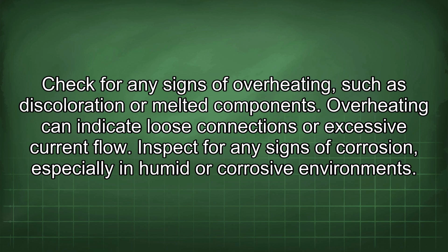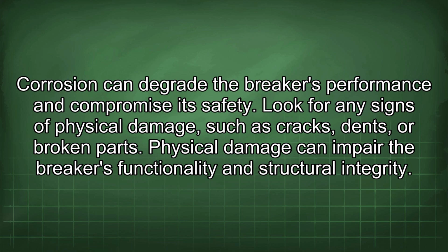Check for any signs of overheating, such as discoloration or melted components. Overheating can indicate loose connections or excessive current flow. Inspect for any signs of corrosion, especially in humid or corrosive environments. Corrosion can degrade the breaker's performance and compromise its safety.